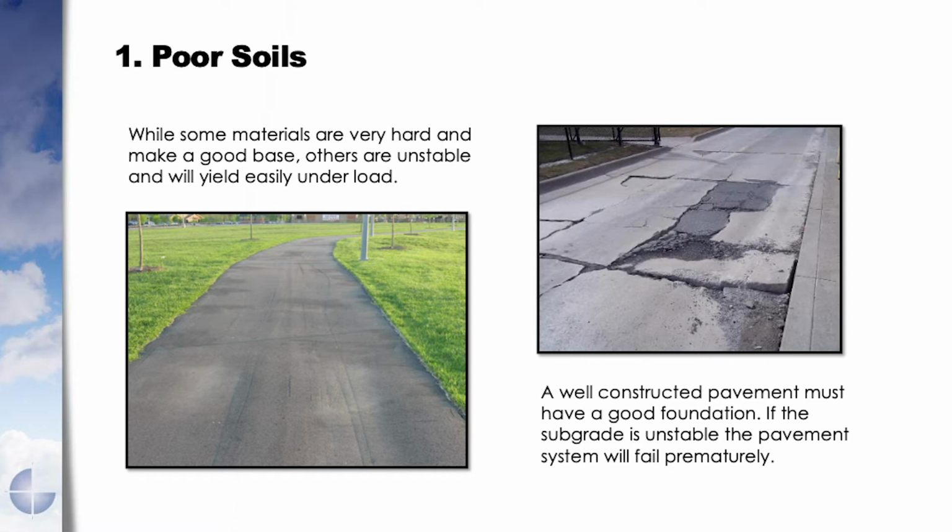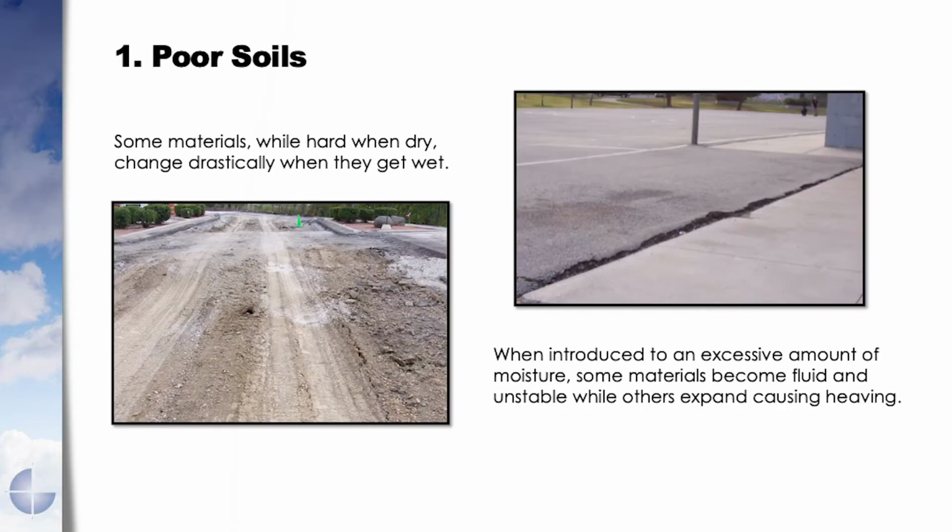Wow. And I'd like to point out, at least on the asphalt pavement, you can see the roller marks. So this was soft from day one when they paved it. You can see the lines running the same direction as the path. Those are marks that were left by the roller. And if there isn't a firm foundation underneath the asphalt, you can't get compaction and you can't get those roller marks out when they're doing the finish rolling.